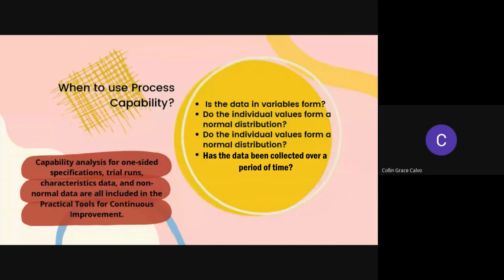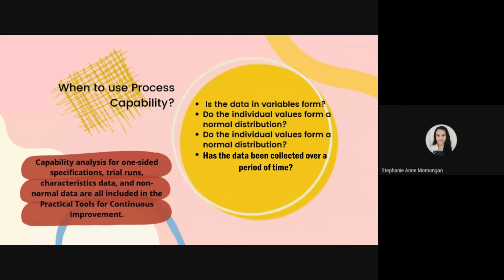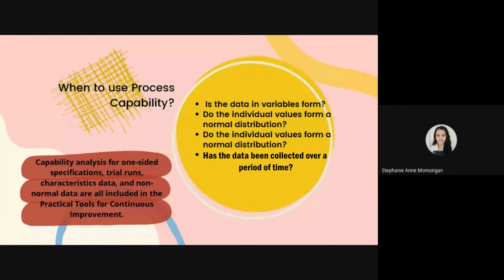Do the individual values form a normal distribution? In order to complete capability analysis using the standard technique, a normal distribution is required. Use a histogram to test for normal distribution. If the distribution is not normal, a non-normal capability analysis may be used.